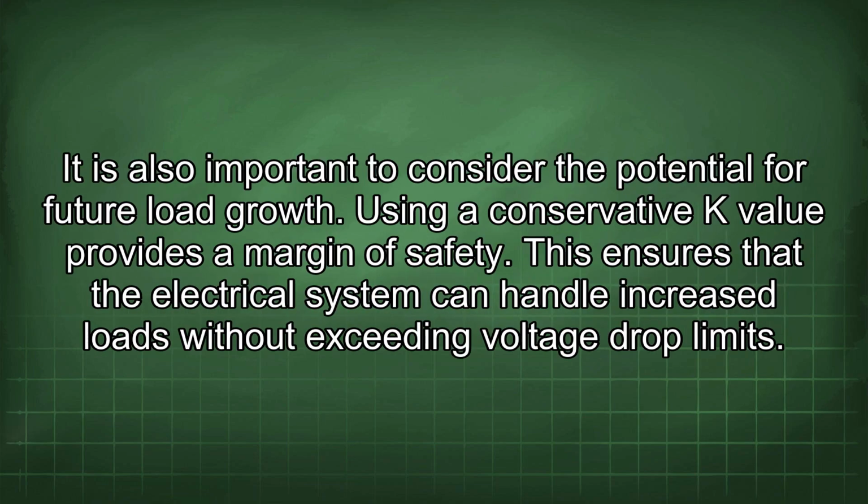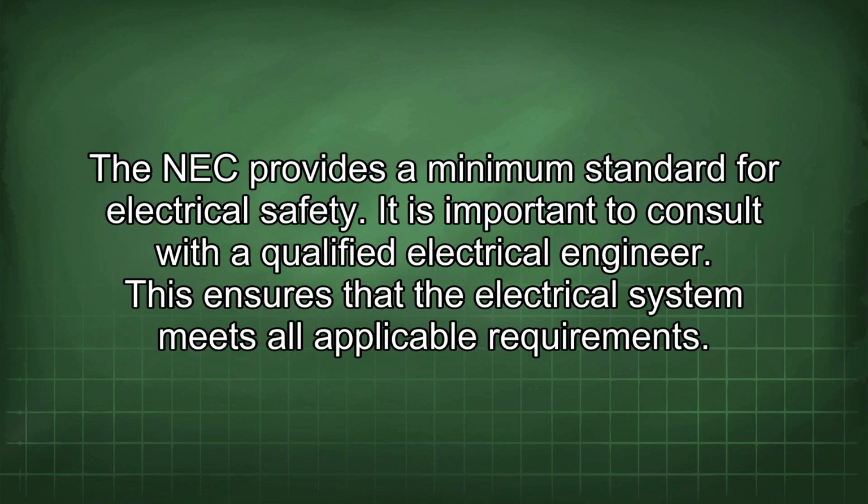It is also important to consider the potential for future load growth. Using a conservative K value provides a margin of safety. This ensures that the electrical system can handle increased loads without exceeding voltage drop limits. The NEC provides a minimum standard for electrical safety.